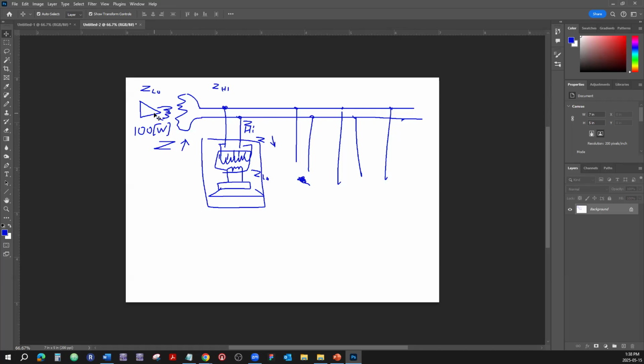Which means that with one, the windings are wound in such a way that at full volume, if you put a sine wave signal, you're going to have 70 volts RMS going there. And of course, the 25-volt system is going to have 25 volts. Both of them work just fine. They just use different currents, but the power transfer is just the same.